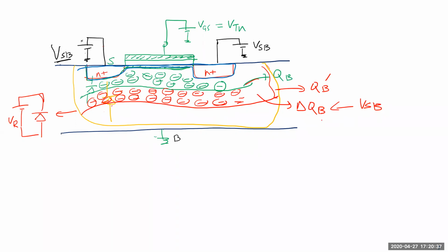So because of which my surface potential changed, and now my VG to invert that channel is a different value. And how do I find that value? The easiest way, or approximate way, is to ask what gate voltage, that delta VGS, I now need to move it back to QB, right? If I put that delta VGS here, then I'll be back to QB, and then everything will be back to where they were. Everyone follows this?